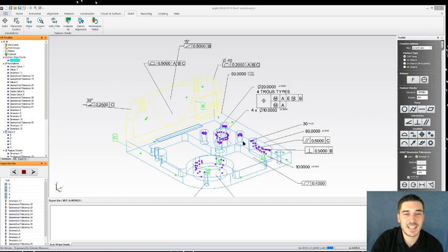So what this is asking is an edge filter setting, and just know that filtering points close to the edges is a good thing. It prevents the software from mixing up which points go with which edge. And in this case, what it's doing is just offsetting, looking off of the surface, first of all, for 1 millimeter, and an edge offset of 1 millimeter as well. That just avoids any data that might end up in the wrong spot. So we'll just hit OK.